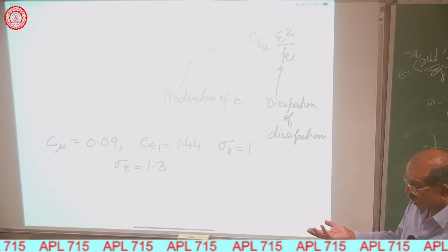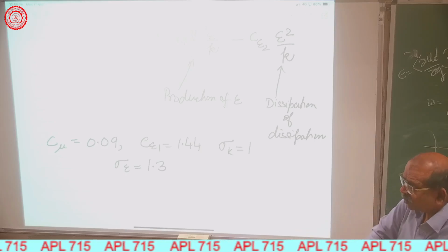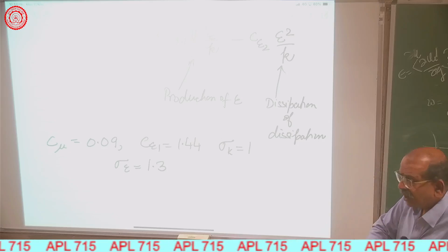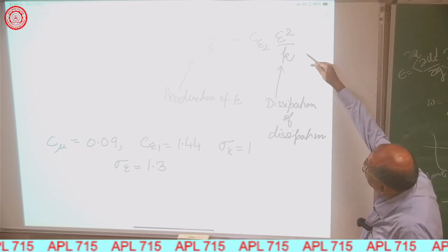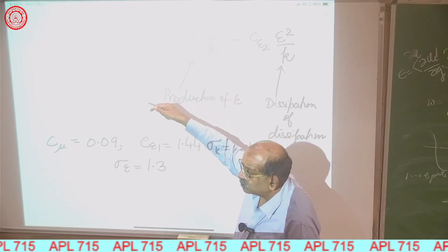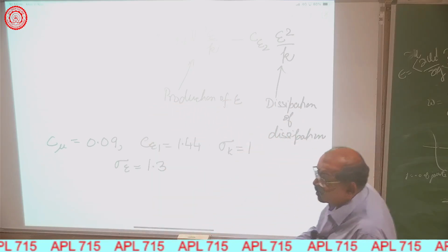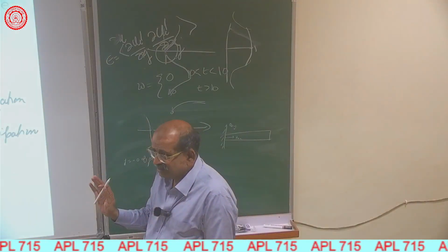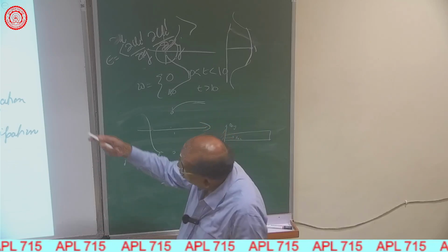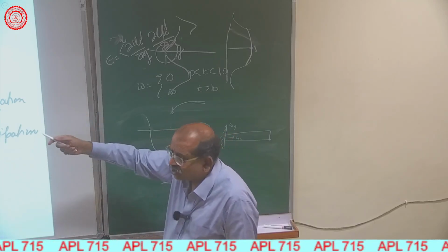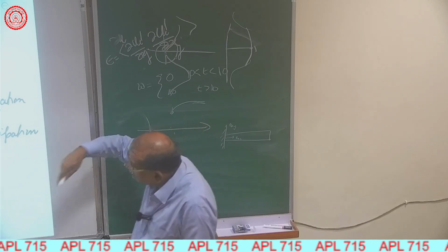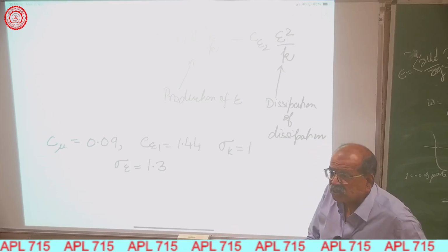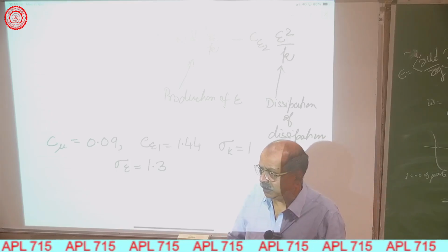You have no idea. You can model this geometry. You can do CFD for the mean velocity. At least you can try and make a grid and solve it. You have an equation for K, you have an equation for epsilon. So now you don't need the geometry except to provide the boundary conditions. And you can now solve any case by putting this equation and trying to solve for this. So in that sense, this model is a complete model.